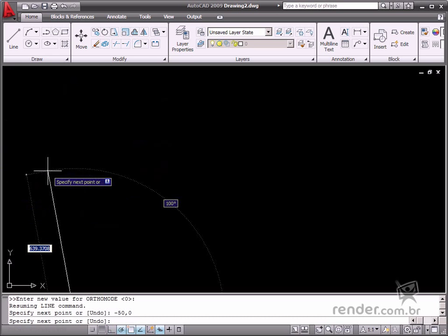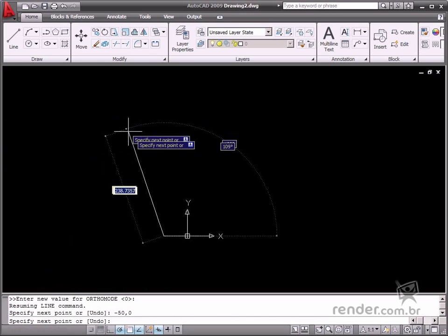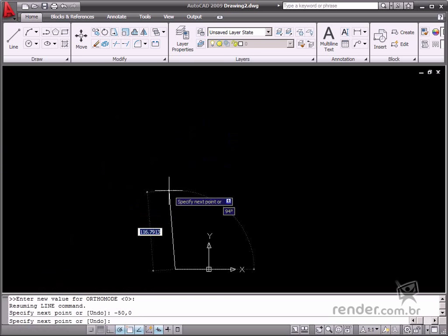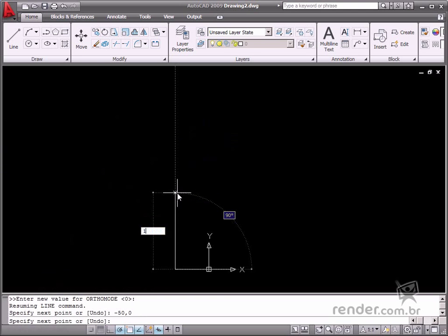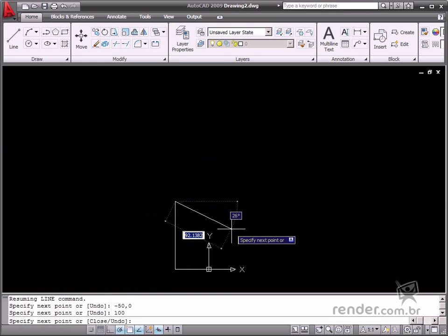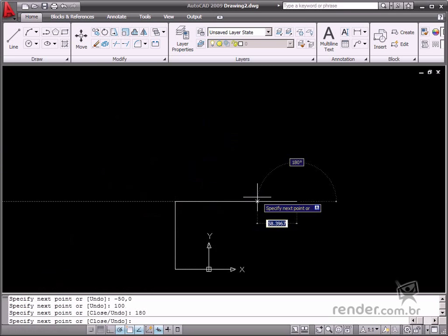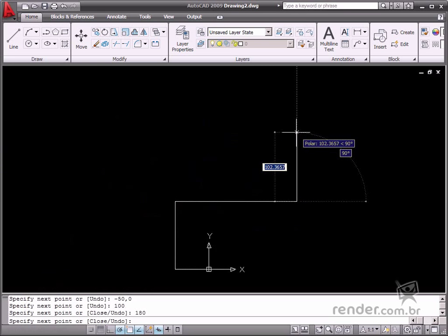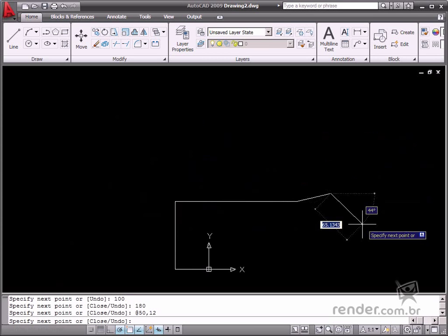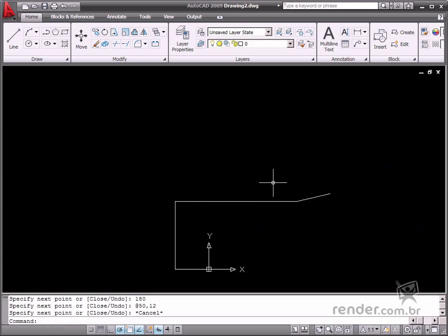Relative is another type of coordinate and applies the last inserted point to base the insertion of a new entity, so in this case the base point is variable. The @ sign, XY, is the format for inserting the relative coordinate system. The base point is used for specifying the coordinate values in the coordinate systems introduced up to now.